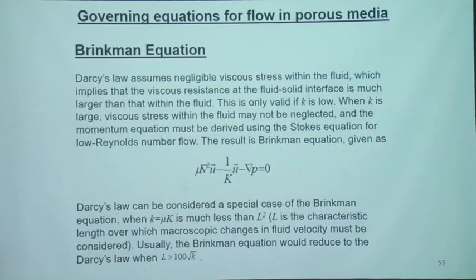Right. In some cases, Darcy's law is not satisfied, so we need to make use of the Brinkman equation. The difference is that Darcy's law assumes negligible viscous stress within the fluid, but in some cases this is not negligible.